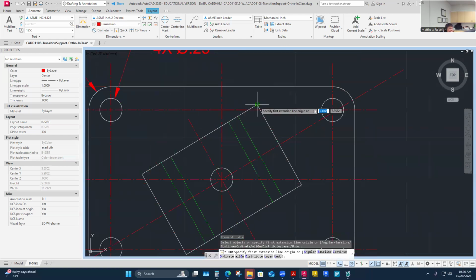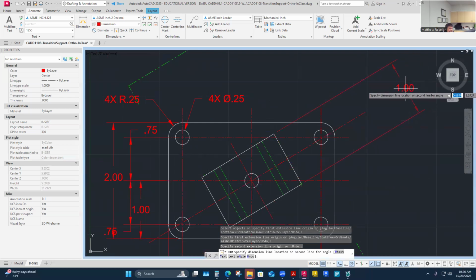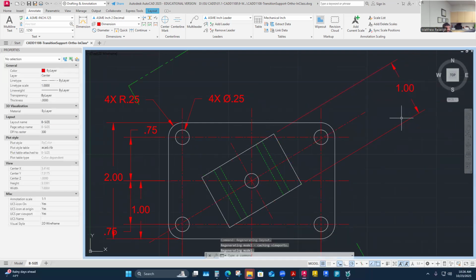This is a dimension that's kind of just to itself, like, hey, it's my front to my back surface. I'm this long. It's a critical dimension to have. I need it. That's the overall width of that part. I'm just going to then worry about locating it in a minute. That's its size. It's an inch. But remember, it's just a size unto itself. It's not located, nothing that's controlled. So it's just this 1 inch size front to back.